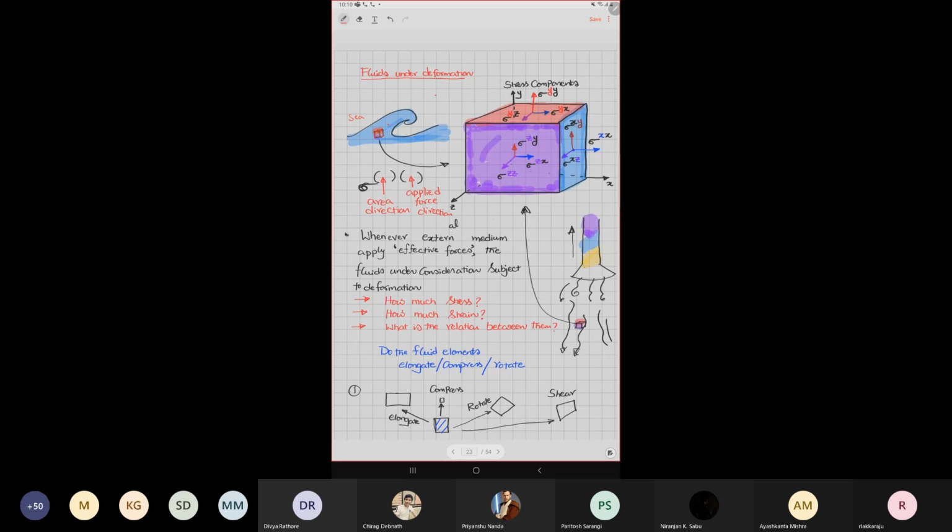So pick that. In fluid mechanics, we always try to talk in terms of stresses rather than forces. Forces are equivalent of stresses. If you suitably multiply with areas and add them up, you will get effective forces. Because of that, it might get accelerated, it might rotate, torques will be generated and so on. The basic nature is stresses will be the basic thing. On surfaces, they will act. Suitably, they add up to create such effective forces. This is the fundamental basis.